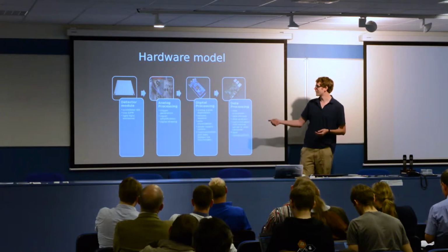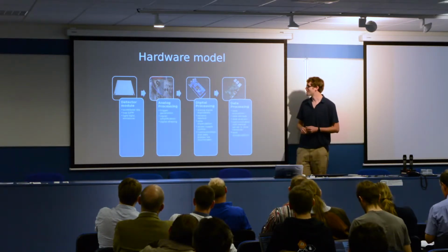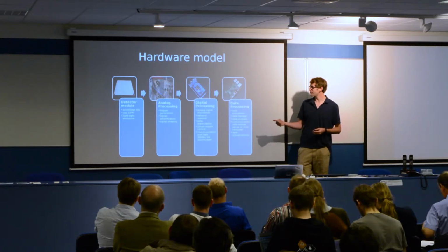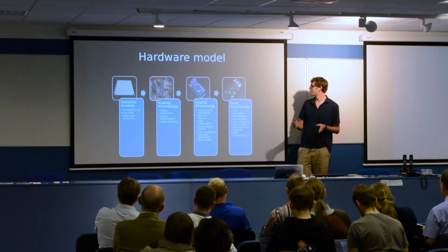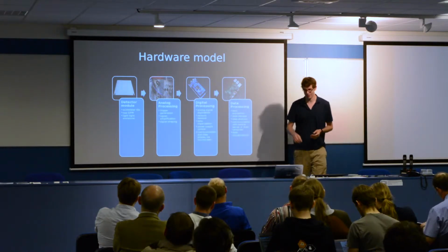We then have quite extensive digital, well, for us, I think for you guys it's probably very basic, where we have an ADC, we read out a bunch of our other sensors, we organize that data into a packet in JSON format, and then we spit that out over USB to a Raspberry Pi, which then runs the rest of our data analysis stack.